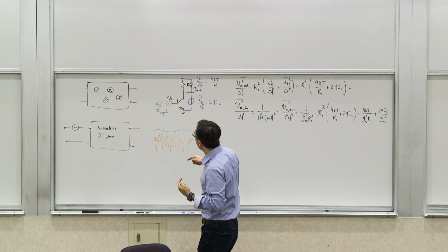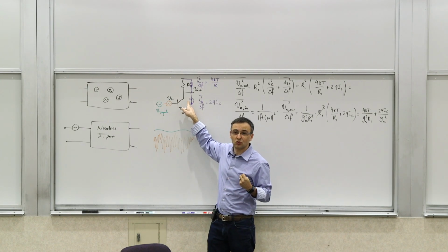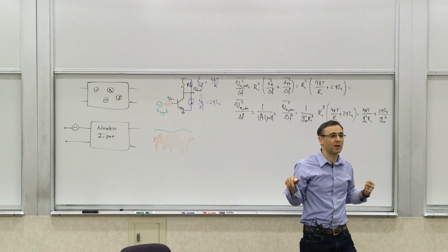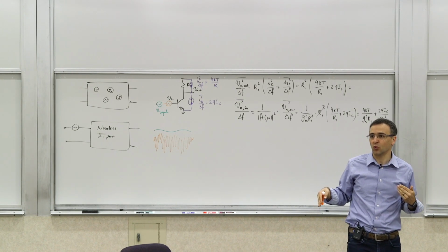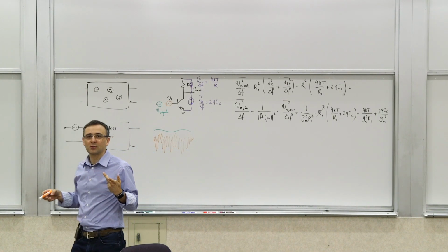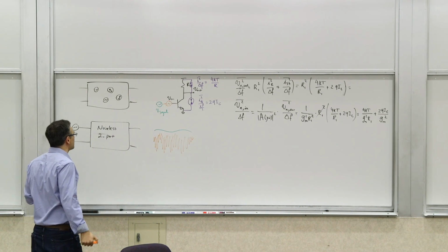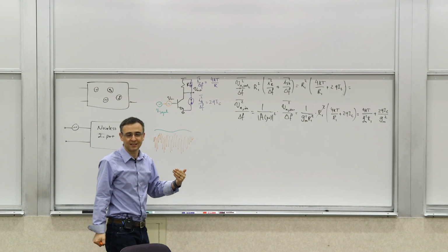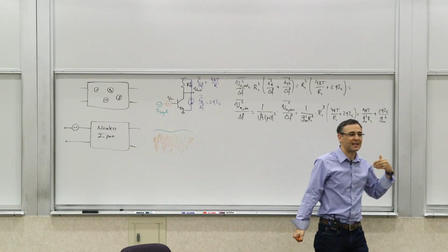Signal design is: if I know what I'm going to do with this, can I design the shape of my waveform so that it becomes less sensitive to noise or other things? Generally speaking, a lot of courses talk more about system design than signal design, but signal design is probably as important as system design. So that's one way to think about it.